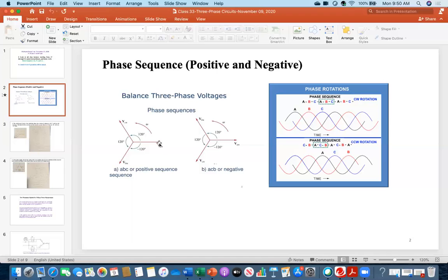When you are connecting, you match phase A with phase A. This is fine. But then you think, okay, I am going clockwise 120 degrees, let's connect this phase to this phase. But you see, this is problematic. This is C phase here, but this is B phase here. And here it is B phase, but there it is C phase. So when you connect A to A, that is fine. But once you connect this one to this one, that is problematic.